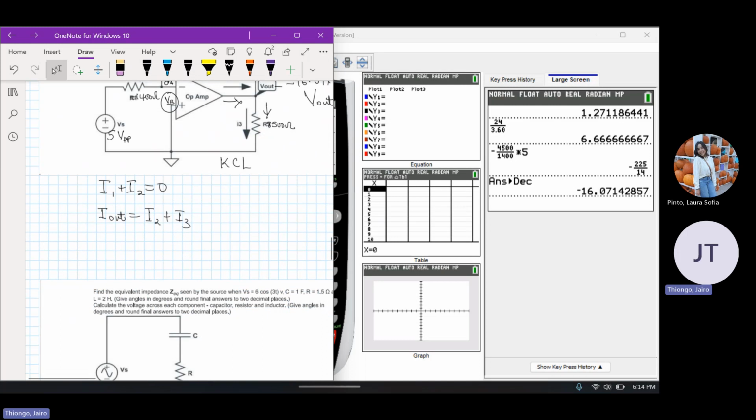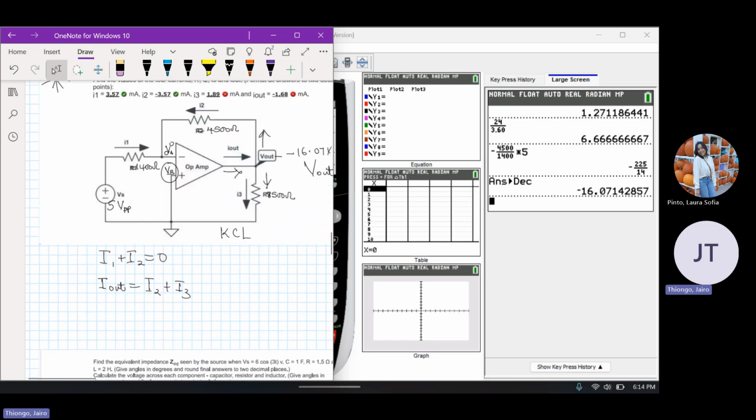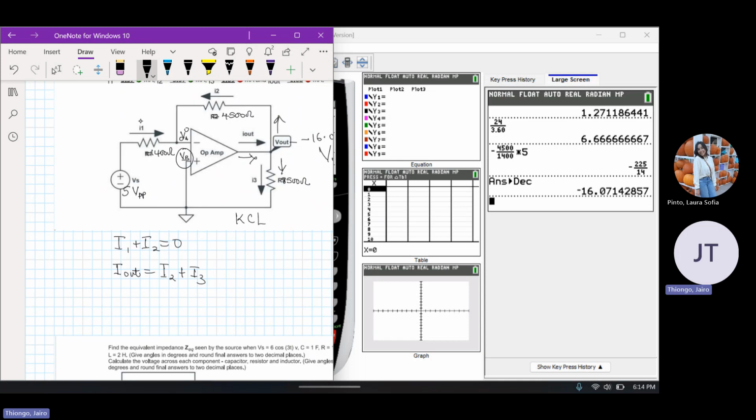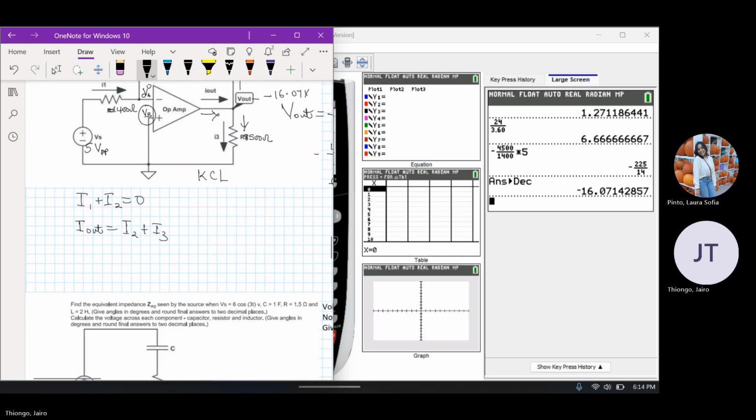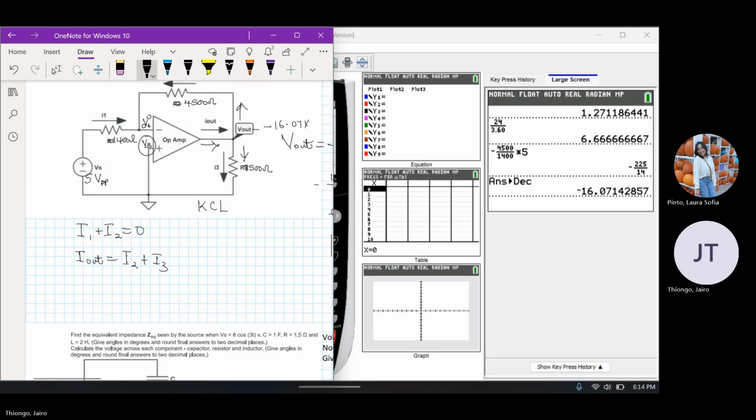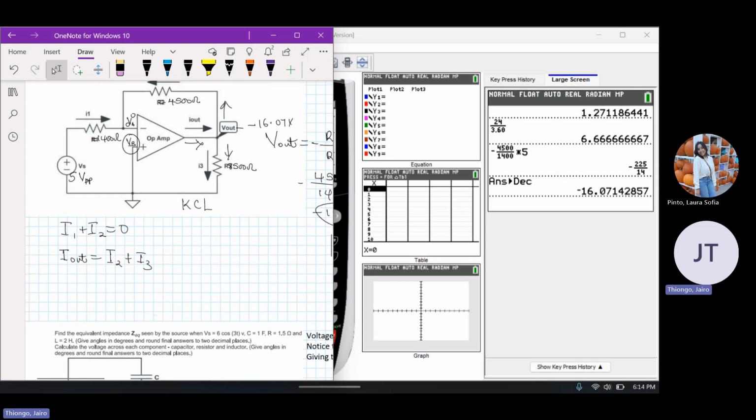So from looking at this, before we touch I out, we can see that we can calculate I1 easily. This is because we have both the voltage input and the resistance. We also have to notice the directions. So let's say, for example, a student didn't take care of the directions. That would be a problem because they would minus the wrong one. So you find the students probably saying 0 minus Vs, but this is not the case given that the I1 is going in this direction. So it would be Vs, which is 5, over current I1.